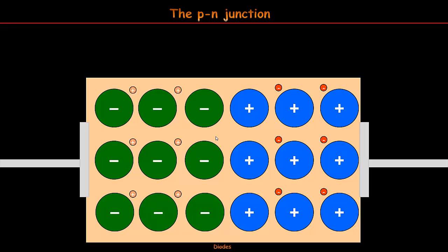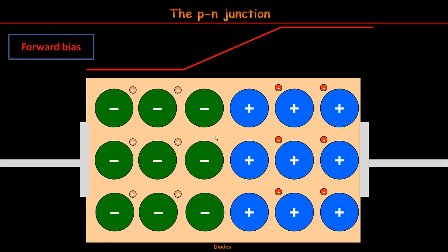Let's bias the junction with a voltage. This is to say, apply a voltage across its sides, allowing or not a current to cross the junction. Carriers are not able to cross the junction by themselves because of the barrier. They do need some help. That help is applying an external voltage, an extra energy that allows them to overcome that electric potential barrier.